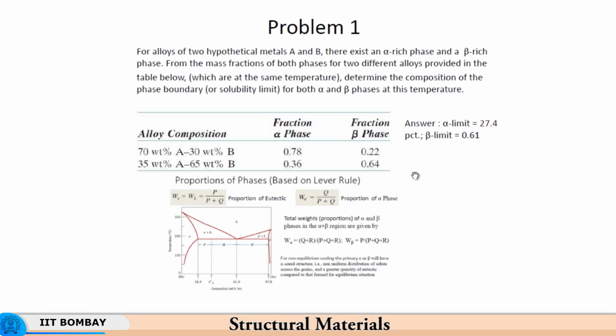These 2 variables automatically get defined once you define these 2 variables. So, actually these 2 variables are not genuine, not independent variables. These get calculated based on the condition that these 2 have to add up to 100%. So, you have 2 variables here and the third variable is the chemical composition, and then you have 3 different unknowns. So, it is possible to solve this problem because of the 3 quantities which have been specified and unknowns being just equal to 3.